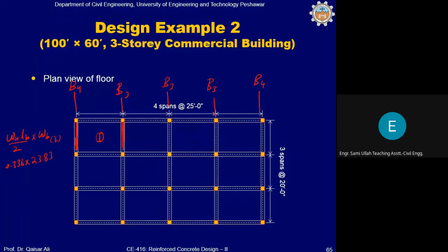because now this is the load transfer along the longer direction. WB for panel 1 is 0.29 and divided by 2. Calculate these, well done. 1.16. So 1.16 will be written here, and it will also be written here. Okay.